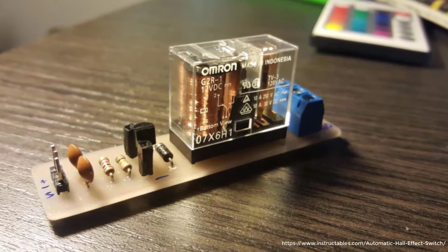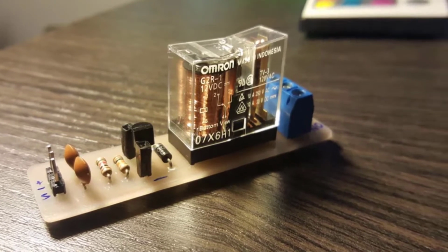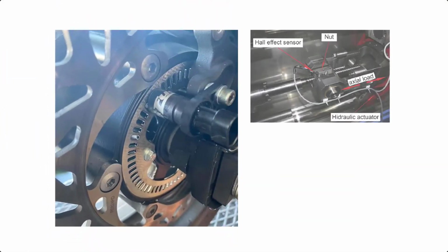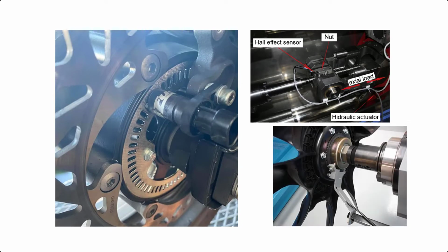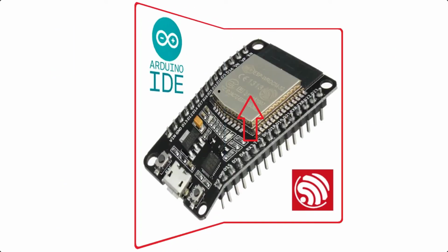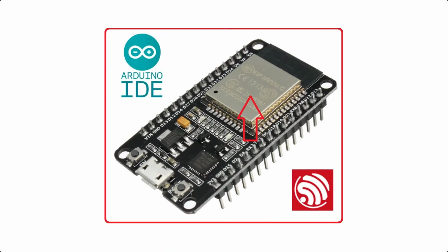One of the common uses of magnetic sensors is in automotive systems. It can be used to count the number of revolutions of a wheel to compute the distance and speed of a car. It is used to calculate positioning, detect proximity, detect closing of doors, and much more. Reading the Hall effect sensor measurements with the ESP32 using the Arduino IDE is as simple as using the hallRead function. Let's take a look.